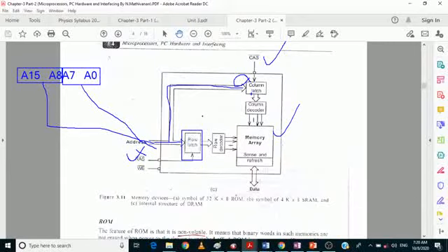When the DRAM is trying to refresh, the memory is looked at in the matrix format. We have the row address as well as the column address. So how the memory is going to be refreshed is the question. Don't get confused. In simple short, we may use the row addresses to enable the memories; whatever memory locations are there in that particular row, all of them are going to be enabled.